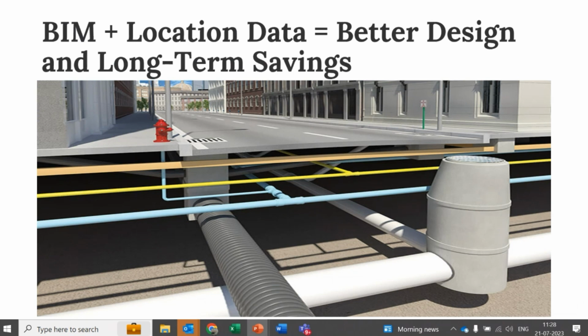Similarly, we can put up the infrastructure in these details. So for any building, if CAD drawings are there and we know what is the depth of each of these network lines, we can even start with the as-built drawings. If it is not available, then we can go with the GPRs. Currently GPR technology is costly, but we can also use the CAD drawings for the particular things. And when we put that in a GeoBIM model, then we know in real time how these fittings look like.